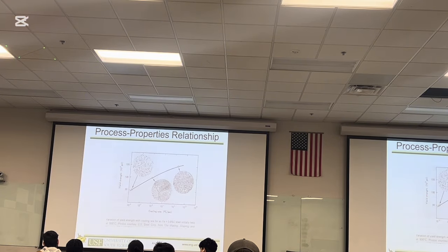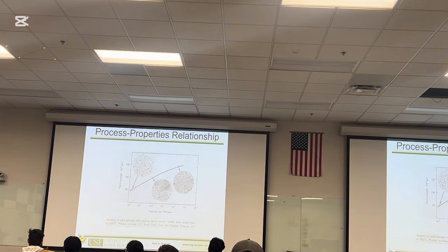And that $1 million question, actually $50,000 question, and $100,000 and $150,000, it's just an older slide from Stanford that shows you the yield strength versus the cooling rate. 3 pieces of steel taken out of the same furnace, same pieces of steel that were cooled in. And what we did not emphasize yet, but pretty much the rest of the class is going to focus on, is the microstructure. So what you see over there is the microstructure of what was cooled at different cooling rates. And you gotta have some sort of magnification device or microscope to look at that. But that is the reason why.